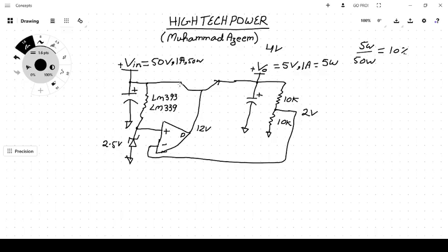So a high amount of current would be supplied to the capacitor to replenish its charge. So due to very high surge current, the transistor would also get hot, and the capacitor would also get very hot, and may malfunction or be destroyed.